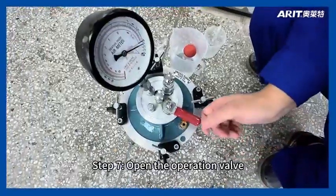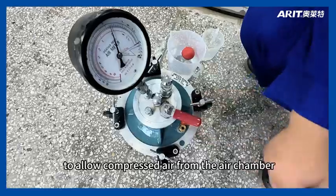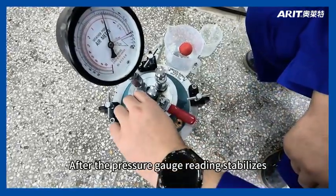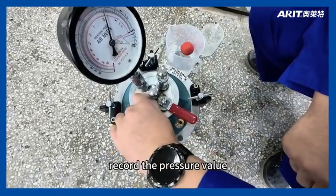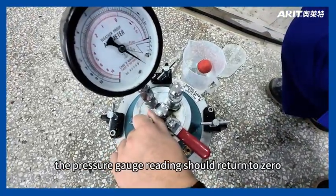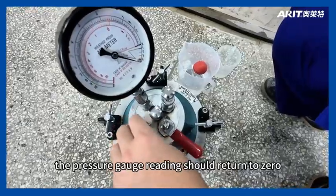Step 7. Open the operation valve to allow compressed air from the air chamber to enter the container. After the pressure gauge reading stabilizes, record the pressure value. Then open the exhaust valve. The pressure gauge reading should return to 0.